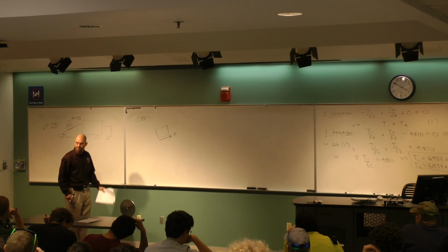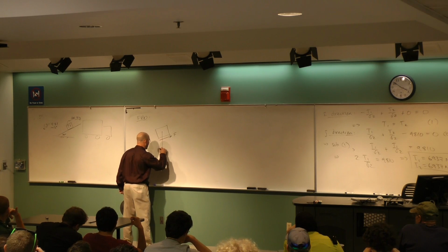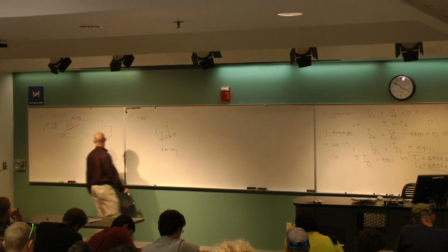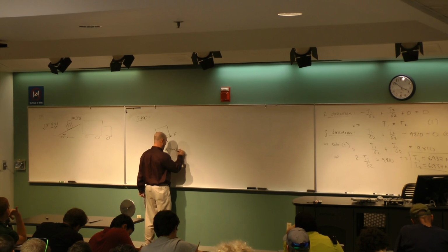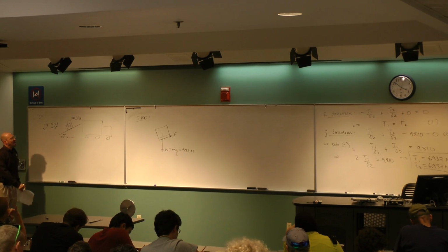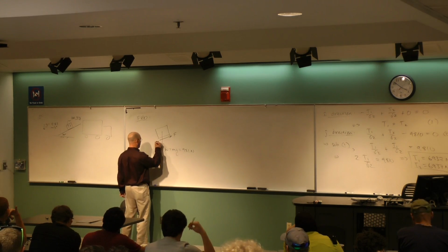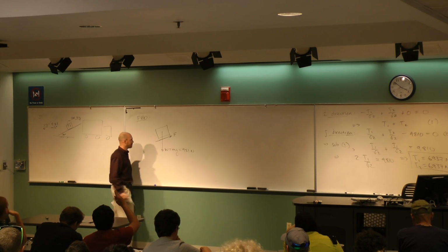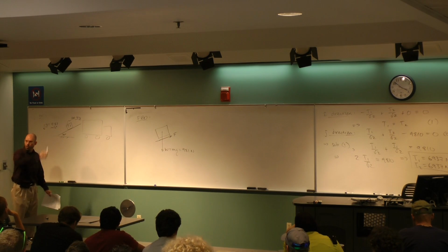So clearly I got the weight. Which way does the weight act? Down. That goes through the center of gravity here, and I got a force down. This is the weight, which is mg. If the mass is 100 and g is 9.81, then I got 981 newtons, down. Then somebody said, well, I got something else. What'd you call that? A normal force. Which way does a normal force go? Up, against gravity. So in the y direction, straight up?